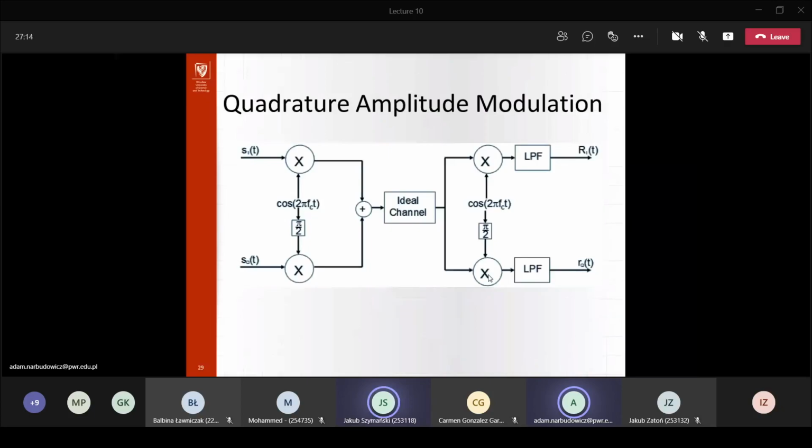Okay. So if we know the error, we can just ignore the crosstalk in the signal processing. Yes, you can calibrate that out, right? Because even if you get the crosstalk, those two will always be orthogonal, right? So what you add to one channel will be subtracted from the other, right?